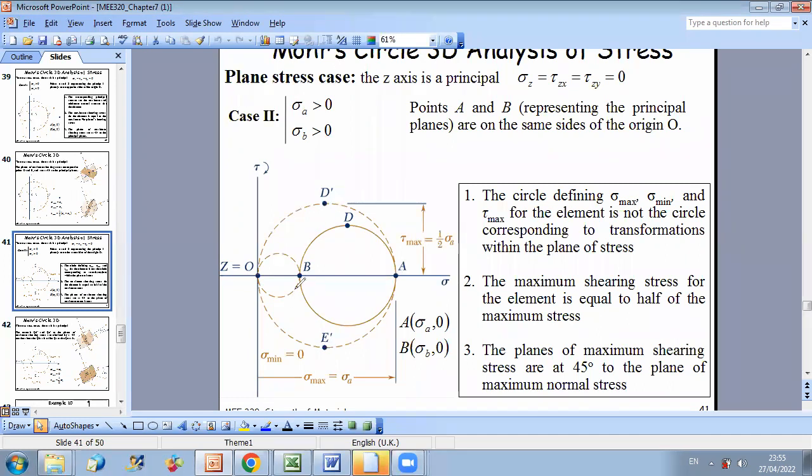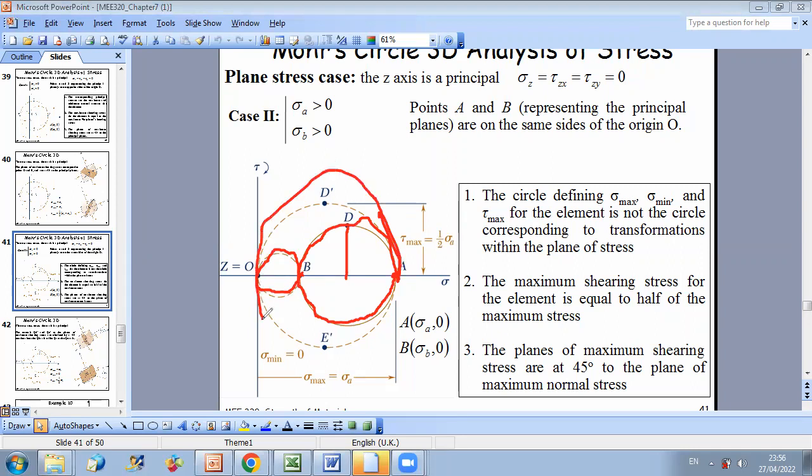If you illustrate the two points, then your maximum shear stress in plane AB is not the maximum shear stress that is possible, because of the three Mohr circles, corresponding to circle AB, circle BO, and circle OA, the largest radius is obtained for circle OA. So we can say that in this case, the maximum shear stress is out of plane AB.